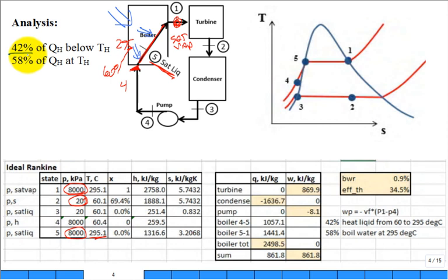First of all, it's a startlingly large fraction of the heat, isn't it? I would have hardly guessed that, right? Just getting the liquid warm, before it starts changing phase. Well, because we introduced state 5, the heating from 4 to 5 is really a difference in the enthalpy. And so the key parameter is look how much the enthalpy had to go up between 4 and 5. That difference is the heat brought in between those two states, 4 and 5.